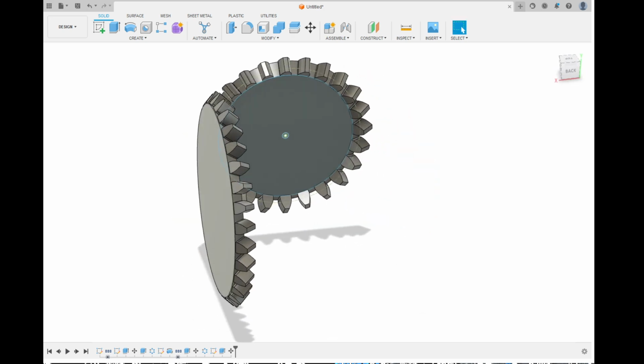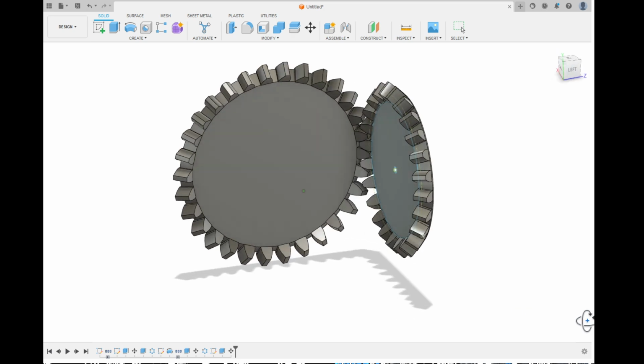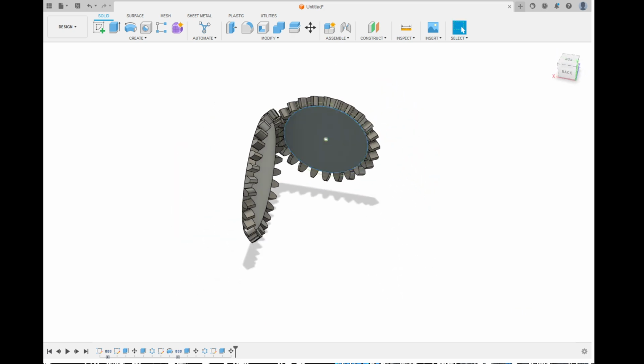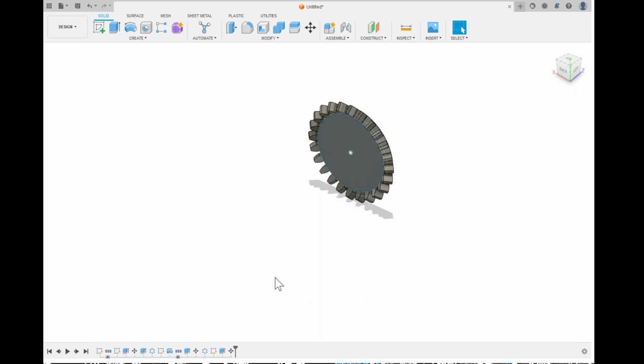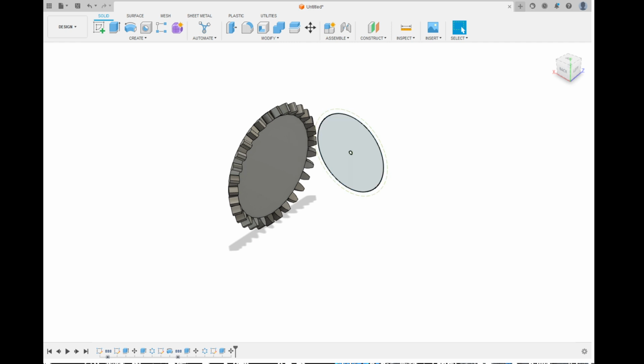And so we can use that same technique to do our other smaller gears, because all the other gears are just a combination of larger or smaller gears rotating around each other. Now, we're going to use this as our foundation to build everything off, because everything that we're building will be coming out of either this body, this is the one that's connected to the drive shaft, or this body. This body's going to have the holding mechanism for the other gears, and it's going to have pins in it, and so we'll focus on drawing those components here.